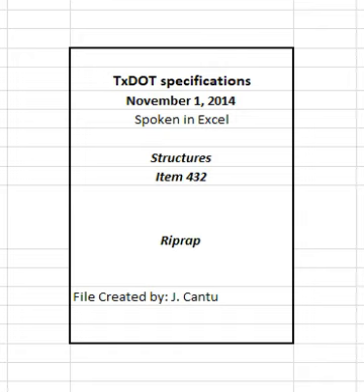Test the riprap stone in accordance with ASTM D5519. Additional tests may be required. Do not place additional riprap until the initial 5,000 square yard of riprap has been approved. Provide grout or mortar in accordance with Item 421, hydraulic cement concrete, when specified.